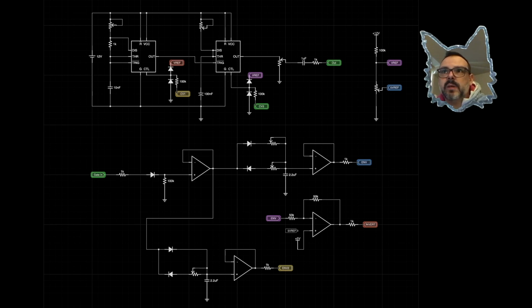The reason for it is that Schottky diodes have really fast recovery times and very low voltage drops. So we're going to lose less voltage by putting it in, since we have to put it in series. Schottky diodes also handle power dissipation much better, so they're really good for filtering really quick transient peaks on the line.